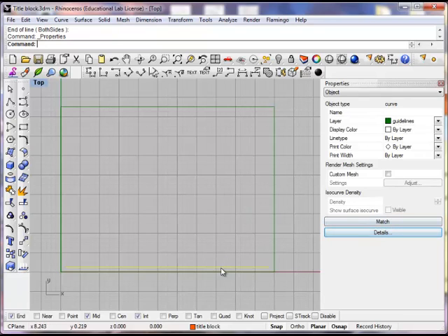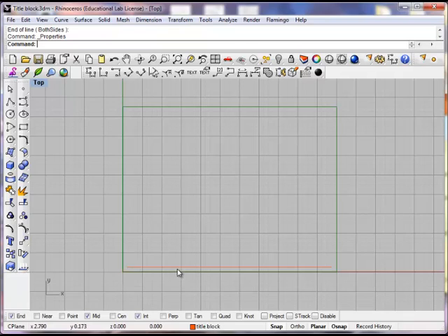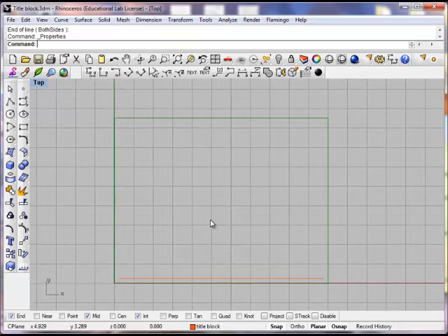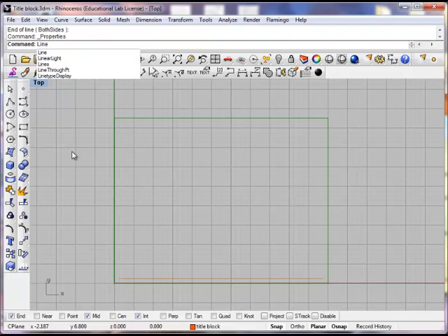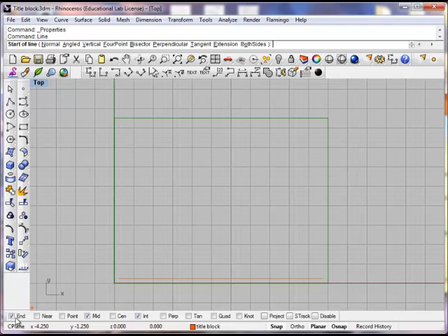What I want you to do from now, it's got it selected, we're going to change that. So click on this little arrow down, and now we can choose and put it on a specific layer. We're going to go to a title block, and then we can close that out, click off of it, and you'll notice that it's turned to your title block layer. And we can begin drawing around the outside of the paper. What we can do now is just begin line, enter,